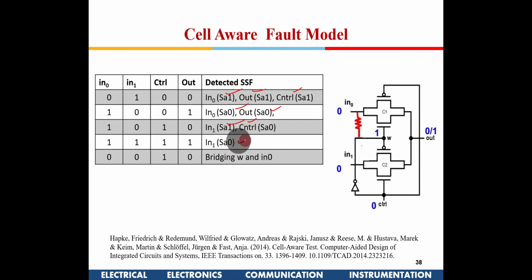Now if the Fab Lab says that over and above this, which is the minimum we will do based on the number of input lines, there is a possibility of one bridging fault also here. Now, suppose I have to start doing open faults and all the other faults, then this test vector will become a big list. But from the Fab Lab the data has come that there is only one possibility during fabrication, that there could be a bridging fault between these two wires.